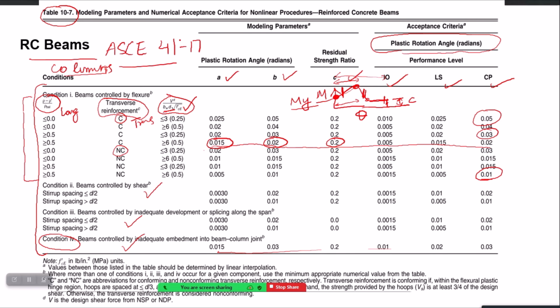So one, this parameter about longitudinal steel, second parameter is about transverse steel, and third is a combined factor, which you can see and again get its value and then decide about which row is to be selected. And it recommends, I think, linear interpolation between different rows.